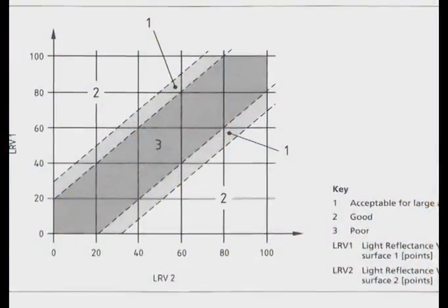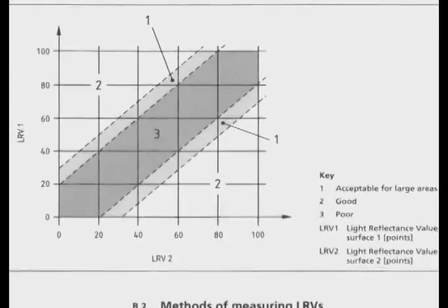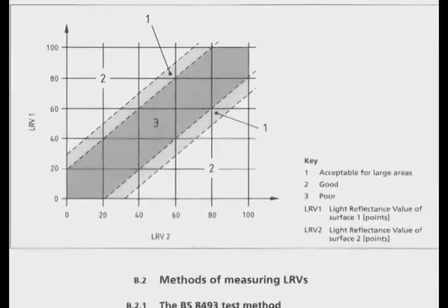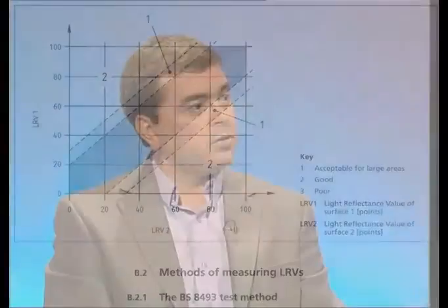Right. And there's also a test, isn't there, on how to test for light reflectances? Yes. The British standard actually gives a table with the light reflectance values of standard colours, which helps architects and designers. But also, it is hoped that the manufacturers themselves would start using the British standard to actually test their own products and publish them with their technical information.